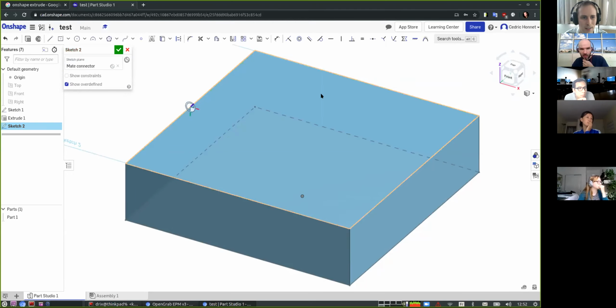All right, I'll reshare. And yeah, so this dotted line here is the sketch geometry that you place in the part. It can be either actual geometry that features will be based off of, or it can be for construction, which basically means that it won't be used to actually make things in 3D, but you can base other things off of it.